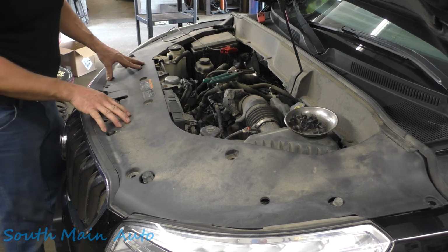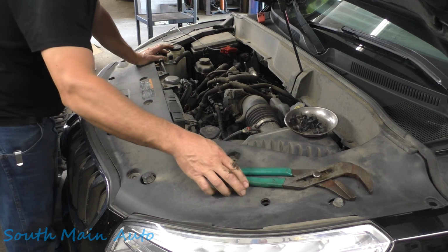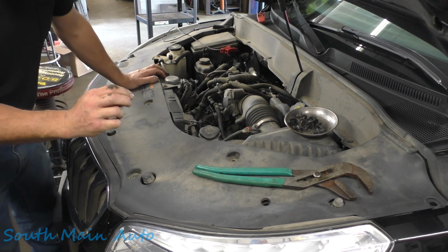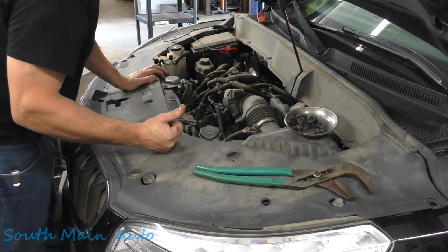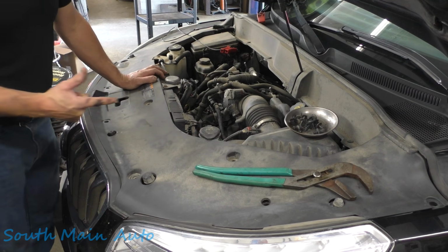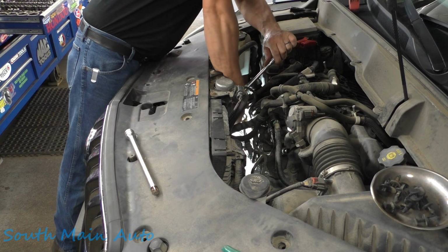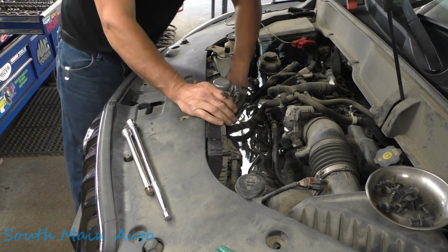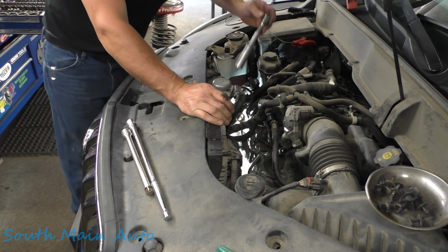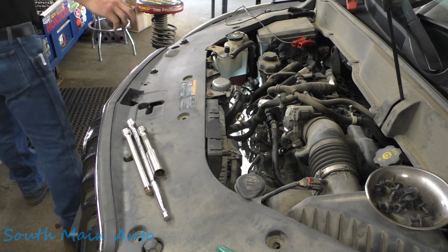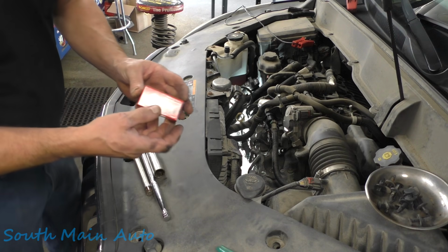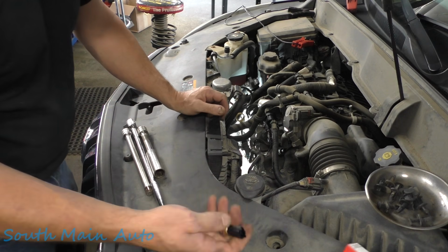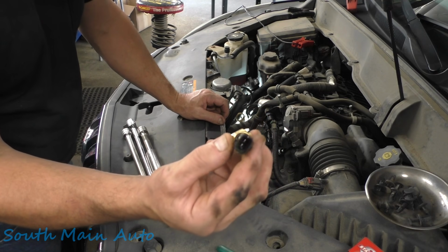It's highly convenient how they hide it under the plastic. I think it's a 3/4 socket. We'll see if we can spin that out and then spin the new one right in without losing a lot of coolant, slash all of it, and without burning ourselves. There's really not much to see, or much that I can show. So I used a 1/2" deep socket so it would fit around the sensor. We probably ought to get the new one first. Also brought to you by Standard. Not a sponsor. They're from Mexico, it says. So there's that. That's all she looks like.